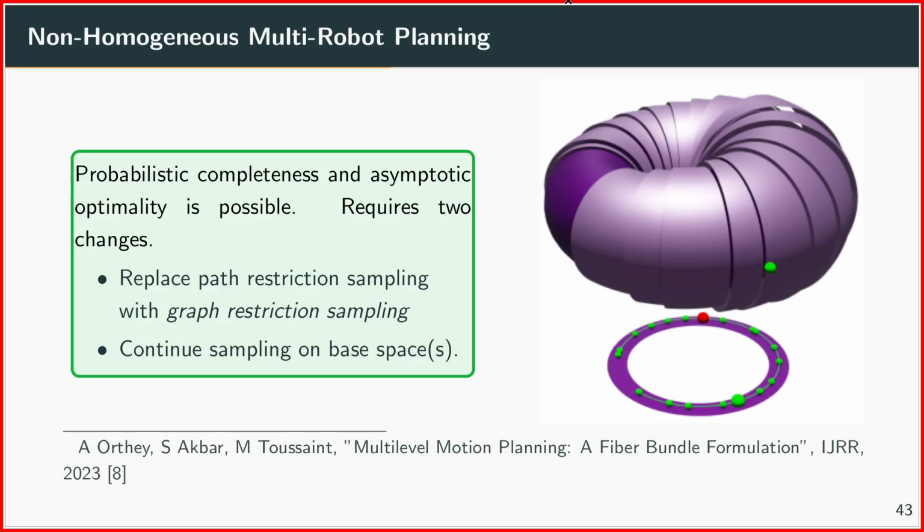And then for each of the edges, you compute this restriction here, and you get some shape like that. And so those are all the regions which, when you have a point in one of those regions and you project them down, you will be on the roadmap here of your lower dimensional space. And those are actually regions which are more important for planning, because you already know that you got a solution here for the first robot. And so in turn, this acts a little bit like an admissible heuristic for your original problem.